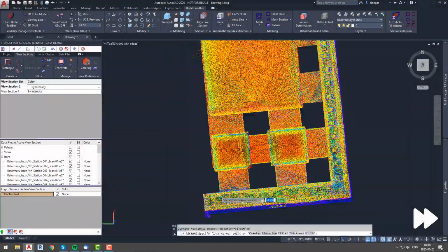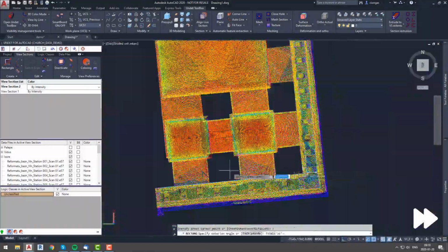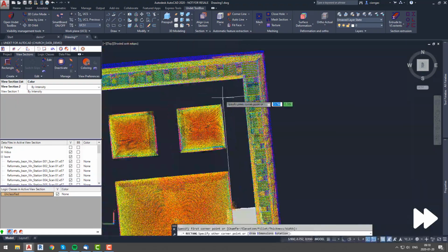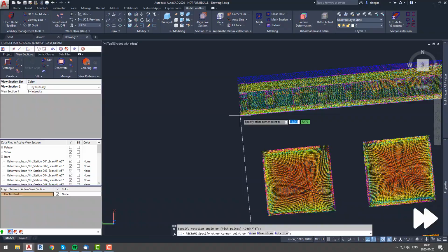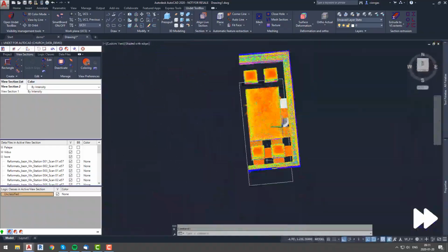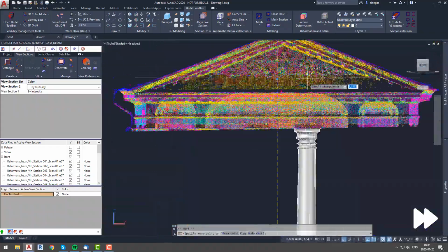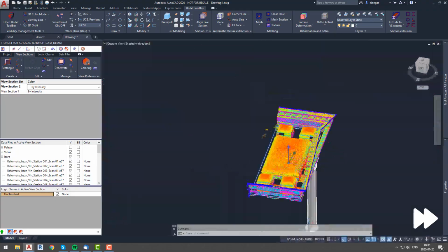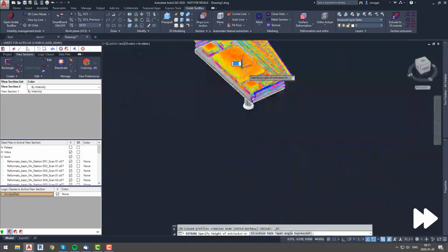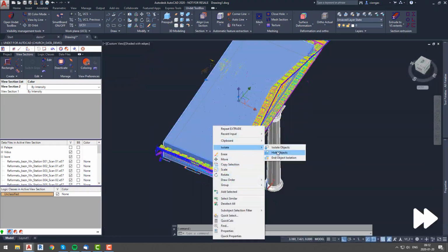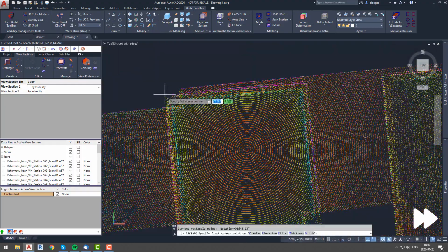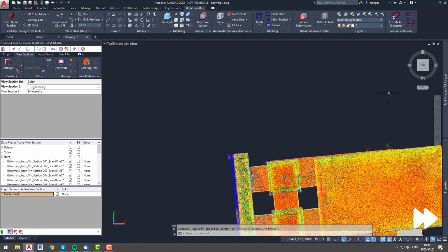Next thing that we will show you will be some vaults right next to columns. To create those vaults, we will have to draw a new rectangle to represent our ceiling. We will adjust that rectangle's element level, and place it right above our column since it is the place where our ceiling starts. So now we will extrude this element and we will have a solid ceiling, but we will hide this element right away since we need to model those vaults.